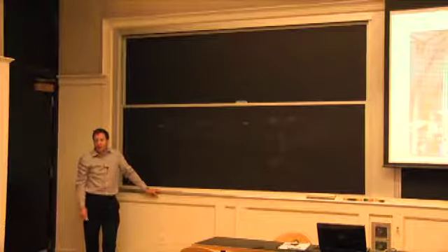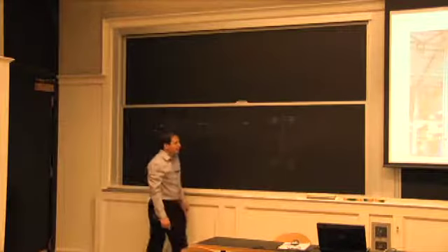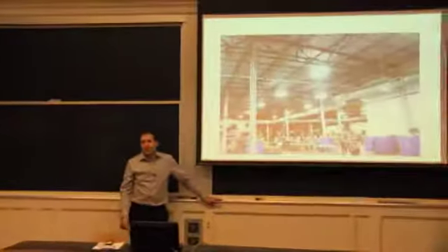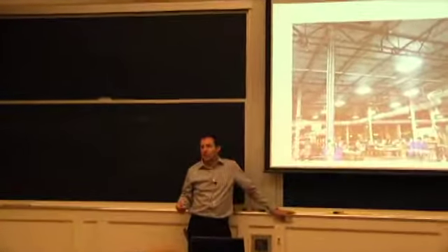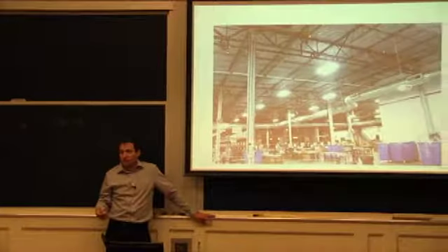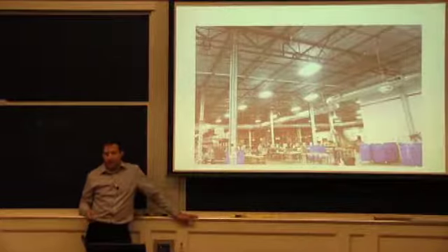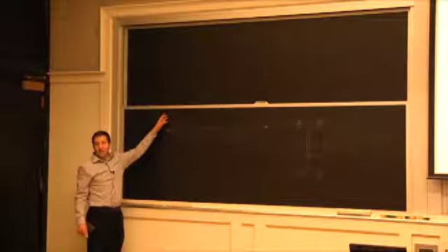If you are designing a roof as a structural engineer, and I don't suggest you do it if you're not a structural engineer, you have to go by very specific requirements for the location that you're building that roof for. And if you have different heights, if this is a large warehouse like Costco and you add an addition that has a different height, now you have to worry about the snow drift.